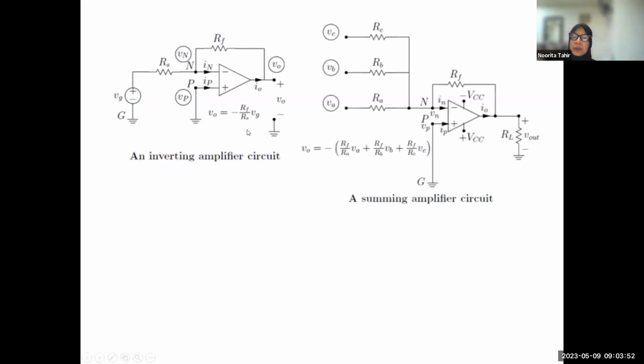Okay, this is when we use the op-amp as a summing amplifier. We input all the sources to the inverting input, and we looked into last week what this negative means, meaning it is out of phase. Not to say that the value is less than 0 or anything, it's not that kind of indicator of negative, but it is to tell that the input signal and the output signal are out of phase.